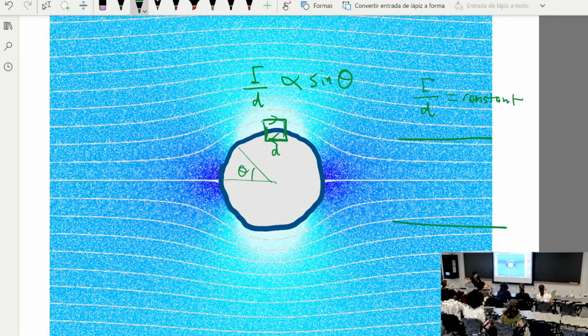So a constant vortex sheet represents a flat shape, while a vortex sheet whose strength goes low, high, and then back lower represents a convex shape. And today we're going to look at even more complex cases of airfoils of arbitrary shape, and look at how we can go from the shape of the airfoil to the distribution of vorticity.